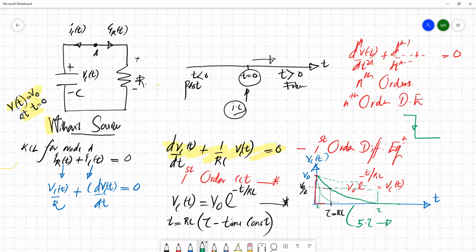If you release the external source and use the stored energy of the capacitor, it discharges through the resistive load and converges to 0, like in the figure. To converge to 0 or to the maximum voltage, it takes 5 times tau.